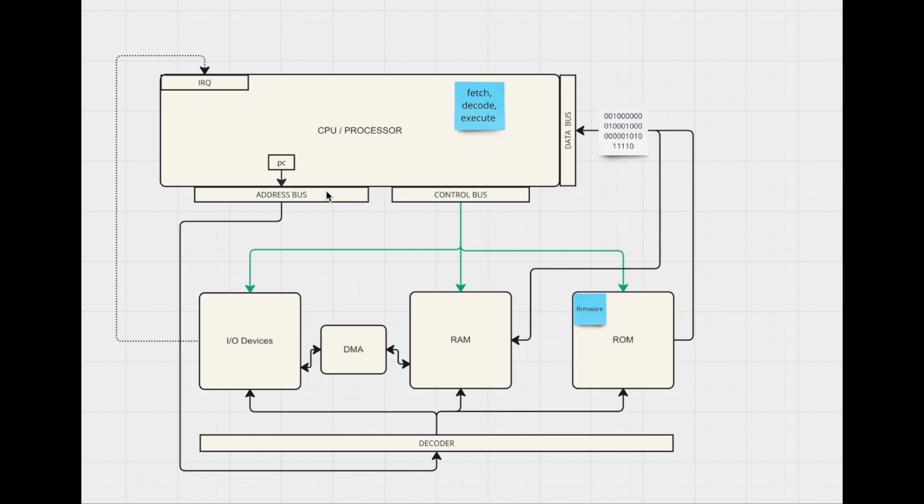And so it sets the address 2 value on the address bus, which again gets routed to the RAM. So address 2 on the RAM gets activated, and then a signal on the control bus is set to write.